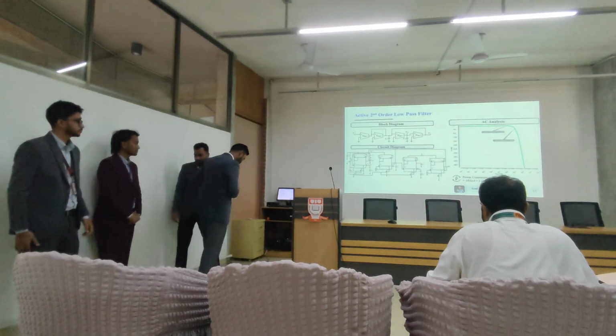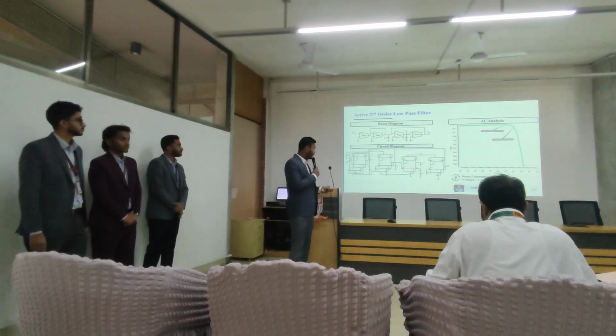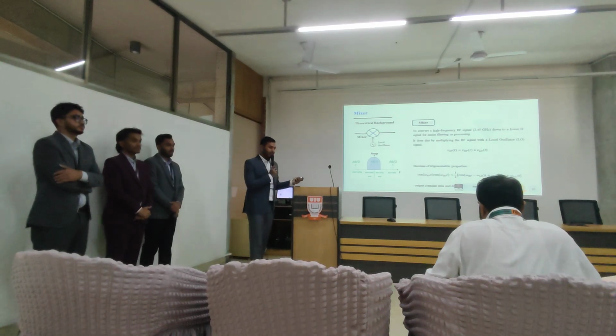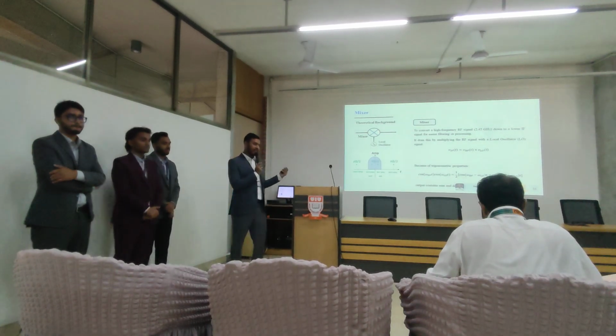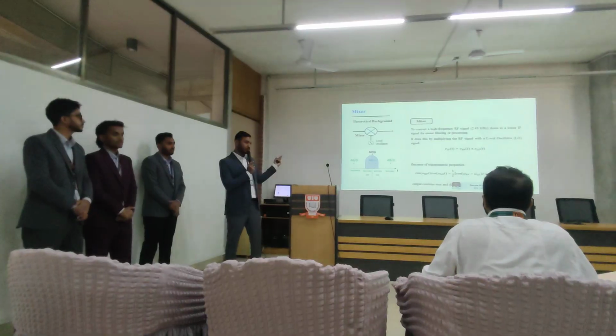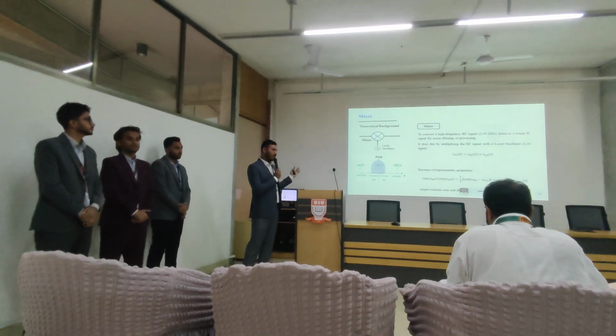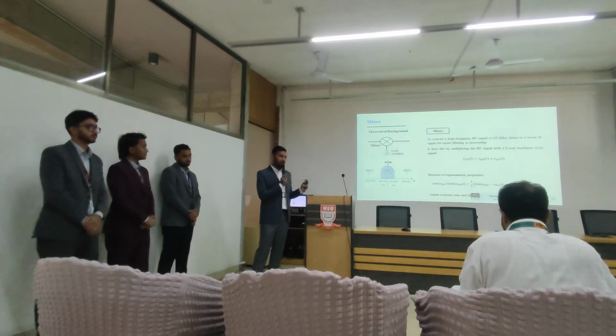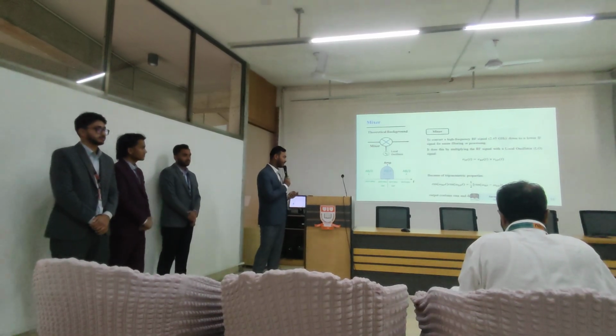Thank you, Ajay. Now the discussion begins with the mixer block of the receiver circuit. The fundamental purpose of the mixer circuit is to take a very high frequency, in this case 2.45 GHz, and convert it into a lower frequency called the intermediate frequency, and this process is also known as the down conversion process.